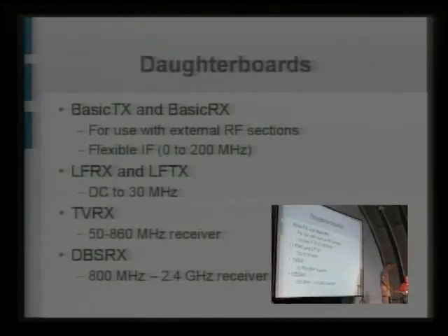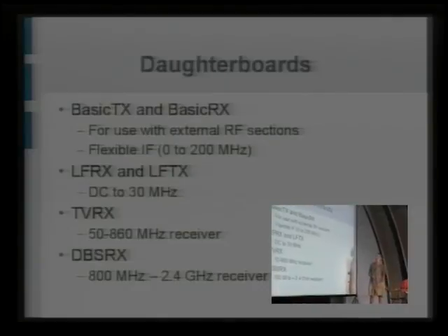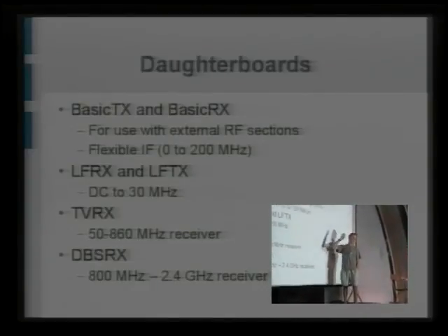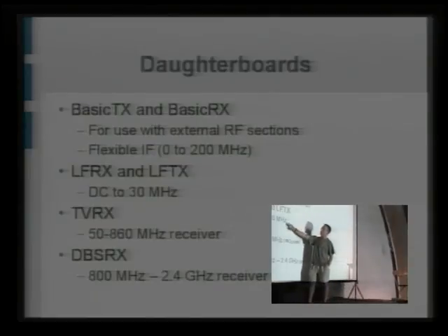Okay, so daughter boards that are available, there's a whole family of daughter boards. There's the basic TX and basic RX. Those are mostly for experimentation if you have your own external RF section. And they can kind of be an interface to the IF. There's the LFRX and LFTX. This is useful for